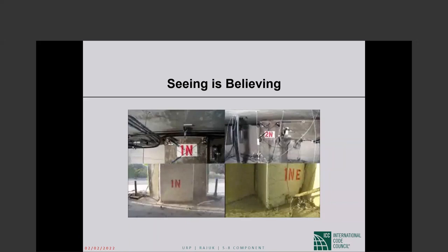How we account for vertical earthquake effect: we increase or decrease our dead load factor. Okay? And that is for all structural members, including foundations, unless there is a specific exemption for foundations, which I will look up.